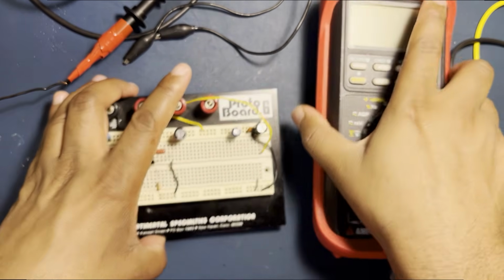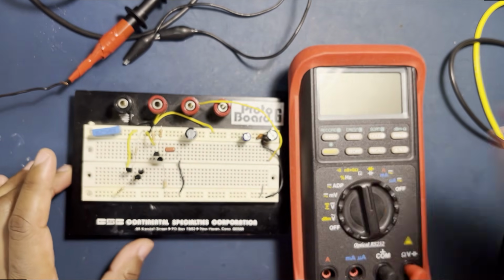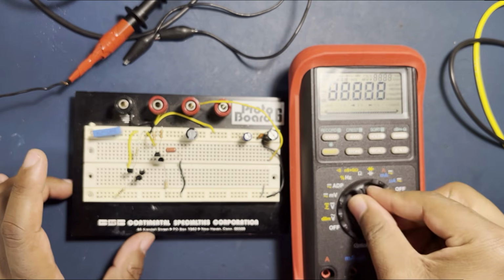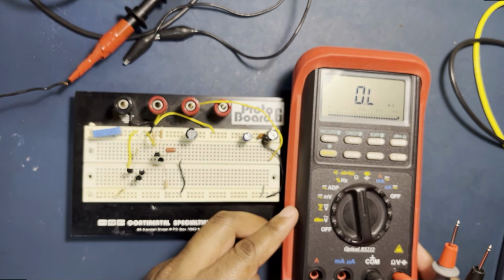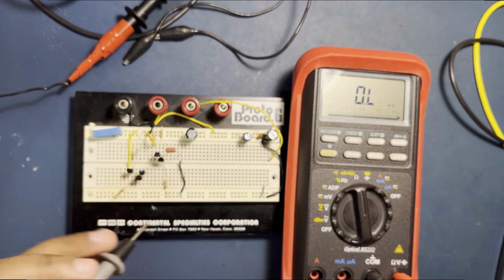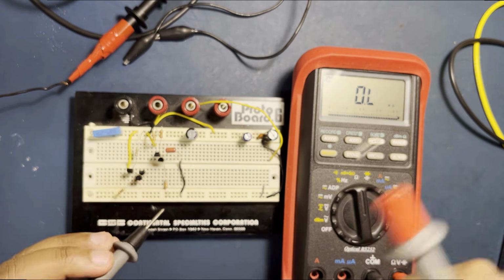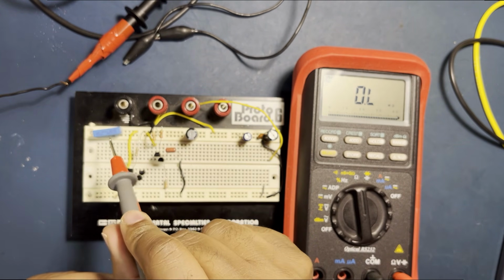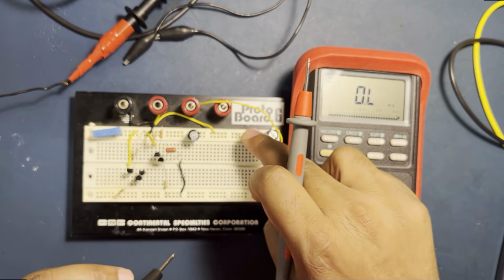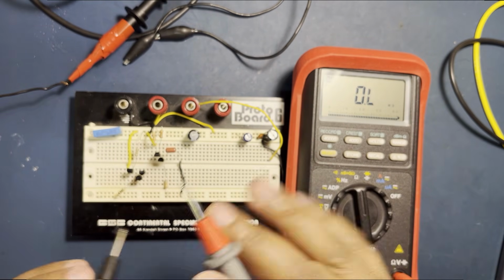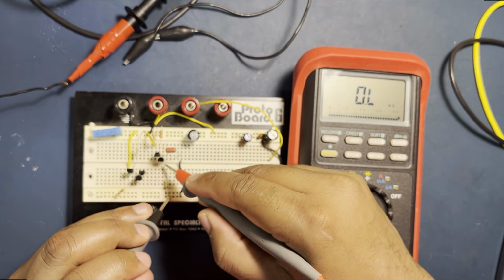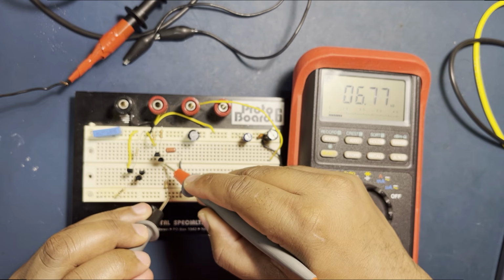So now let's do quick measurements with all the resistors here. Okay, so hope this is visible. So some of these will be slightly off because they are in circuit, right? There are bypass capacitors here that are going to charge or discharge during this testing, but let's just quickly test. Here's my 6.8K resistor. There you go, 6.8.